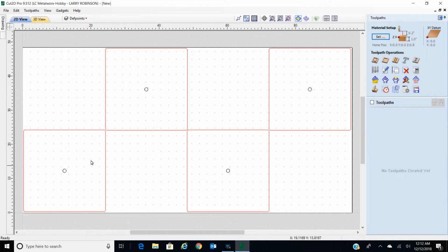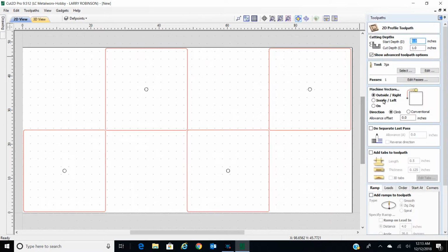And remember, there's 2 different layers here because you've got your center part and then this layer here. So just go to toolpath, outside contour. This is what we talked about, Parker. This is your outside cut, outside contour. Just like they're showing right there, and you always want to be going counterclockwise on an inside.